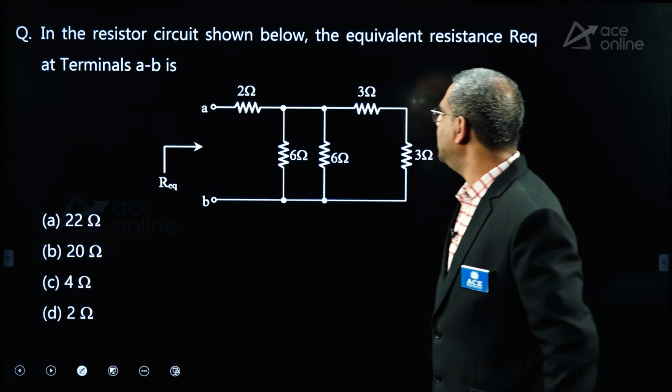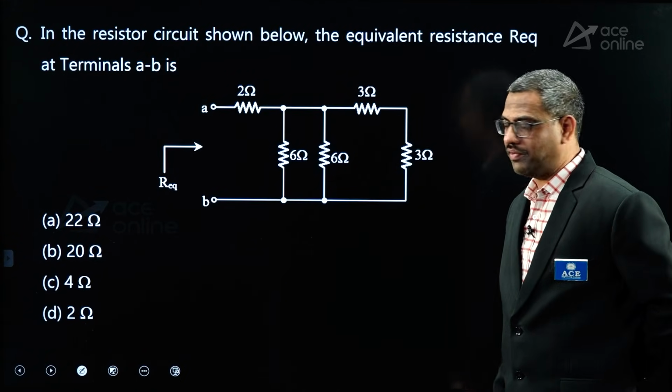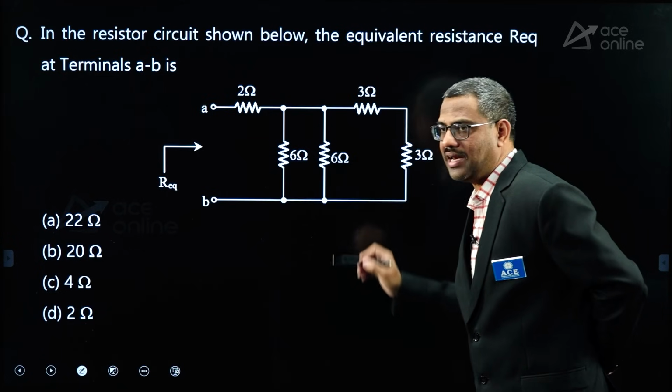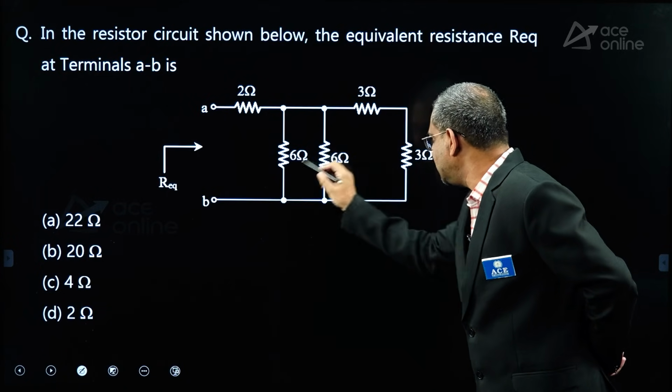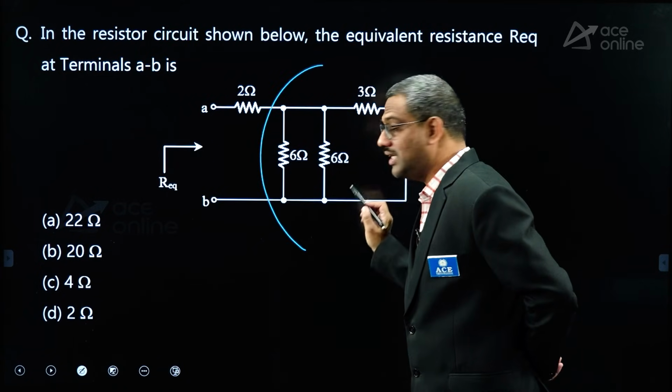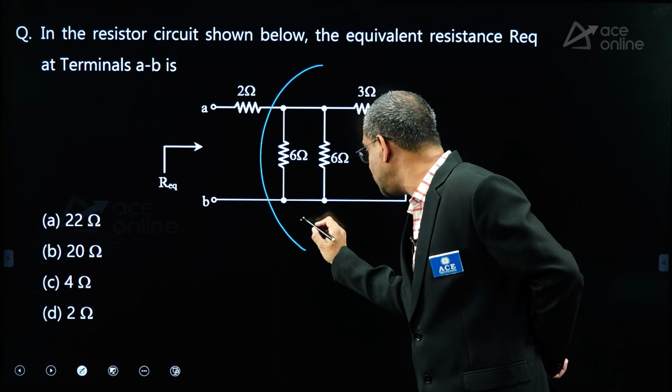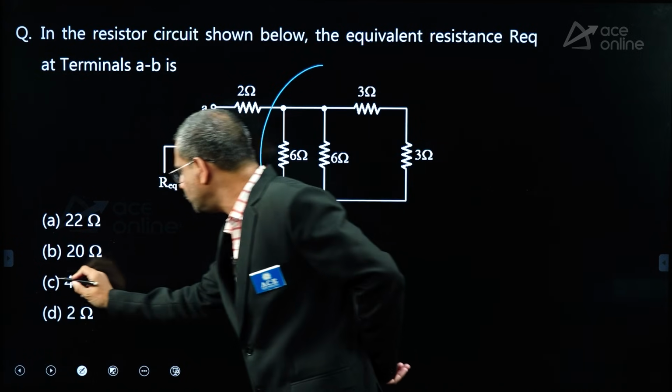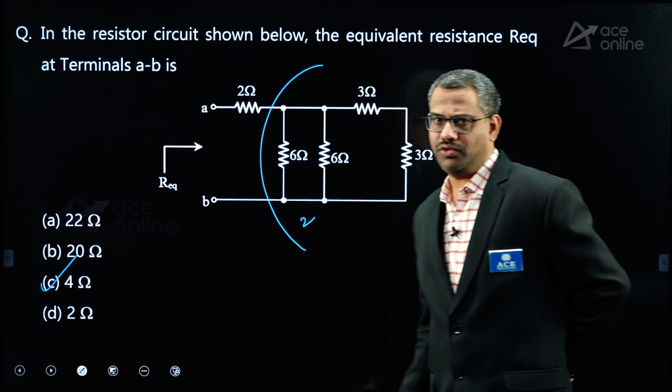Now the resistance seen in the circuit. I want the equivalent resistance. Now these 3 branches are parallel. 3 plus 3, 6, 6, 6 parallel. Resultant is how much? 6, 6, 6 parallel is 6 by 3, which is 2. 2 plus 2 answer is 4 ohms.